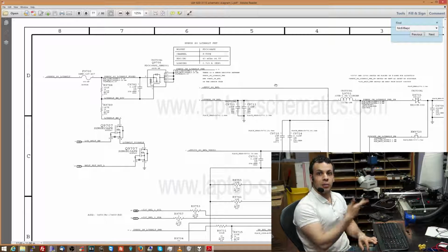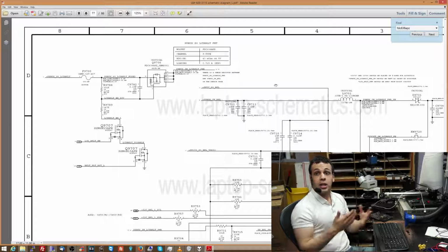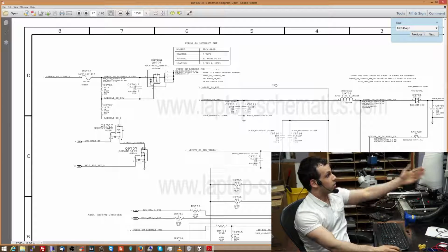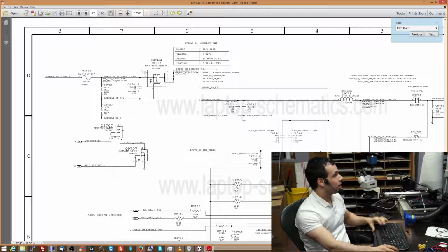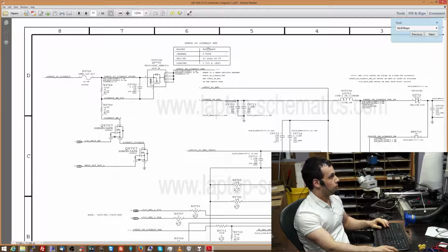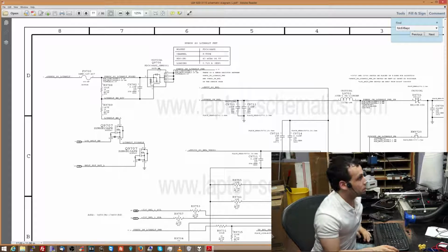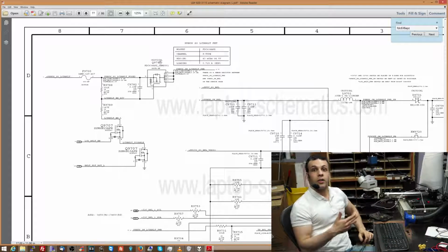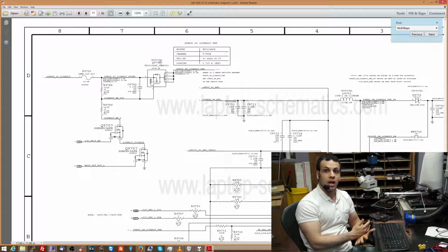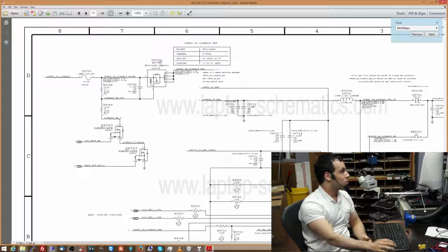So being able to tell a P-channel MOSFET from an N-channel MOSFET, knowing what these two things are, and also knowing how to use Google in your brain to look this up is also going to be very helpful. So you can simply take that number over here, that FDC638APZ, Google it, and figure out from the company's data sheet if that's a P-channel or an N-channel MOSFET. Technically, you should be able to tell if it's a P or an N-channel MOSFET just from looking at the little internal picture in the diagram.